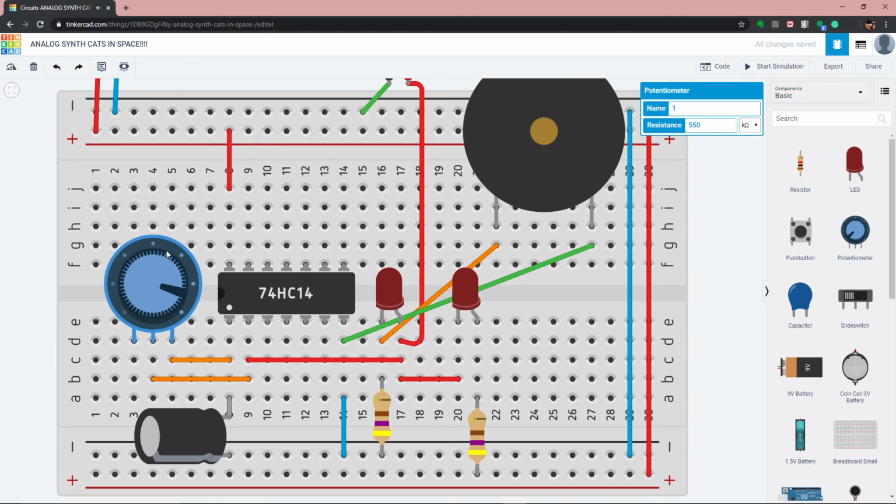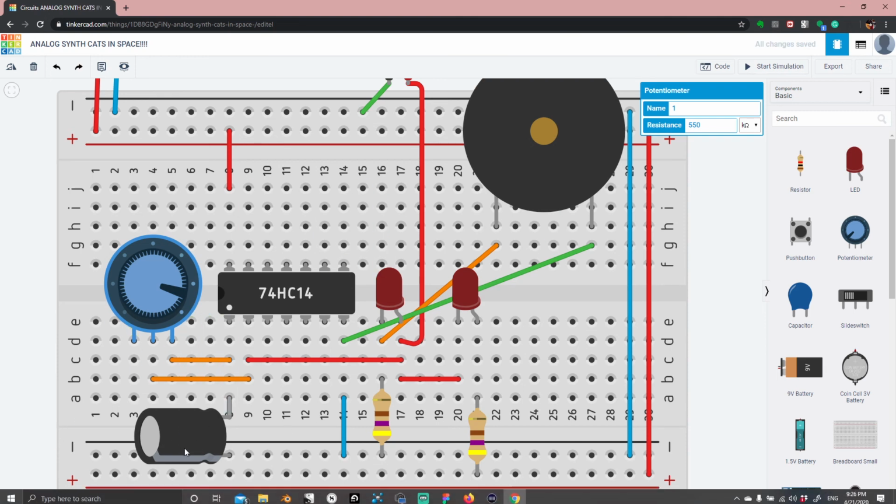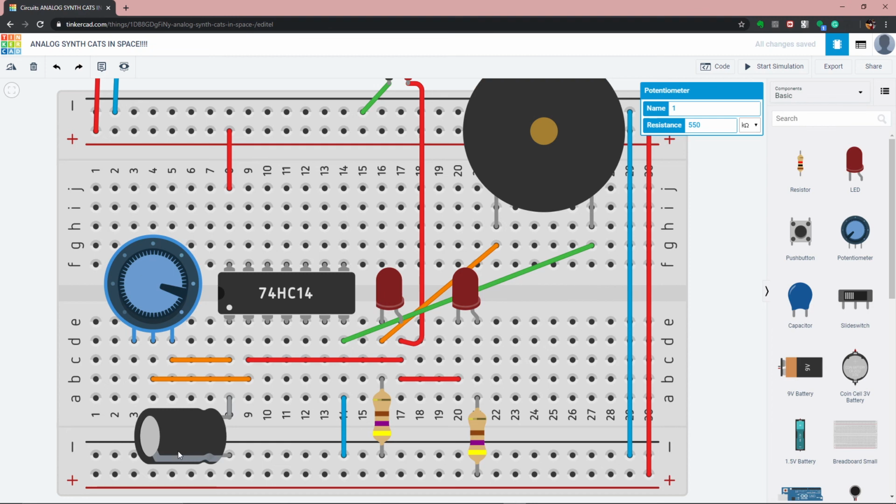Very fun, right? And you'll notice that this capacitor, the stripe, as I promised, this is the negative side, is going to ground. The positive side is going to the first pin on the oscillator. Then, exactly as in Nicholas Collins' schematic, one side of our pot, as we know, the wiper is here, right? So as the wiper goes across the capacitor and gets closer to this point, there'll be less resistance because it'll just be that much, right?